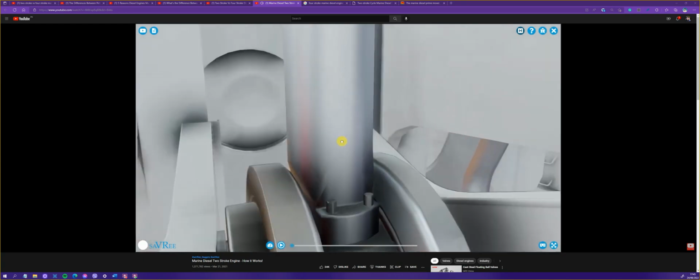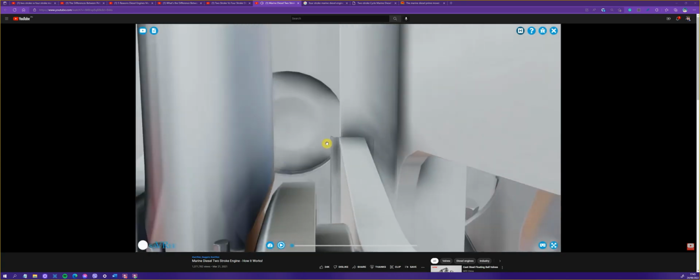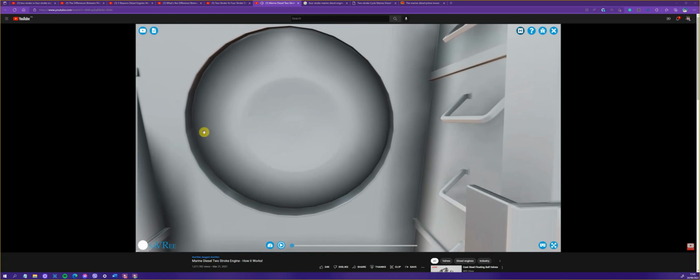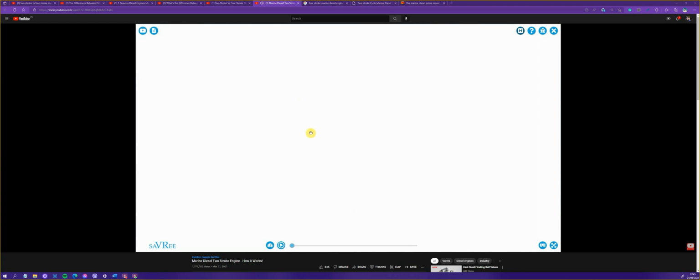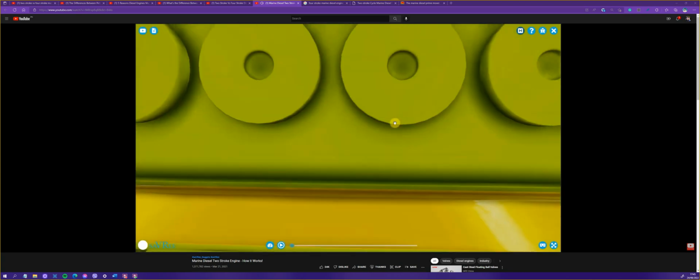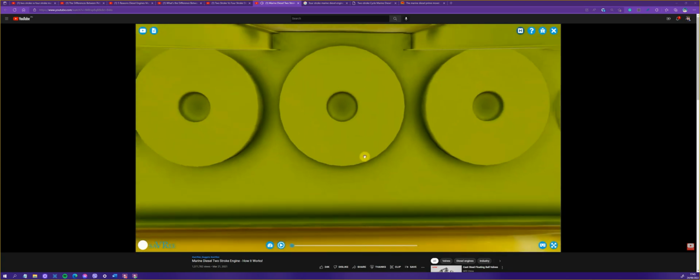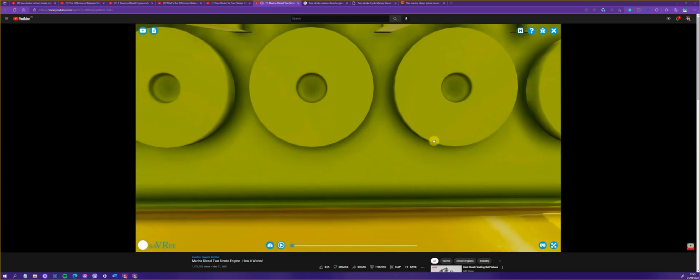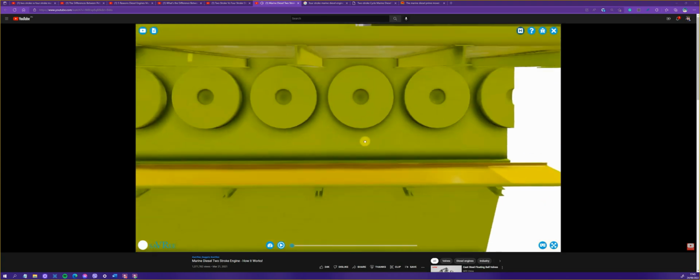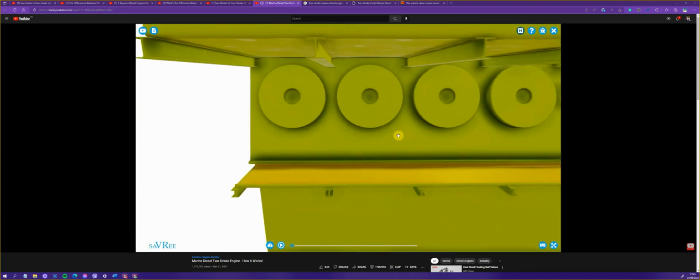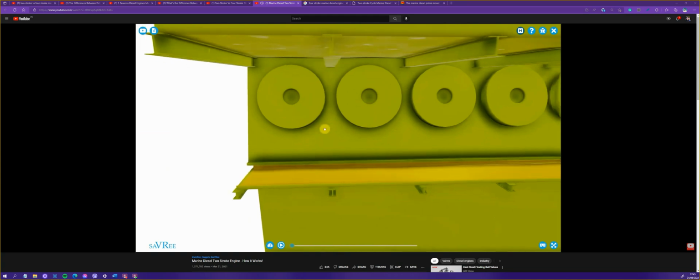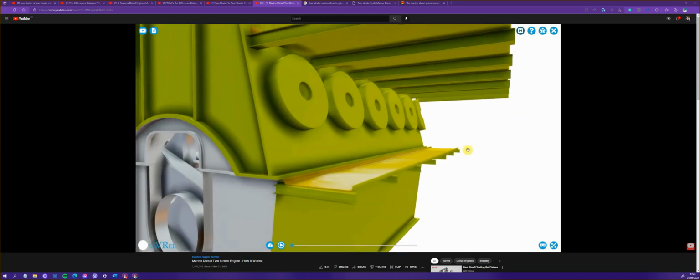Notice on the other side, go over here, this item is not a crankcase door. Let's just go out of the engine. You can do a little spin. So what is it? If it's not a crankcase door, why do we even have it? You can see there's quite a few of them. Well, the reason we have them is because they're what are called crankcase explosion doors. I know, doesn't sound very good, does it? Another name for them, which sounds slightly less terrifying, is crankcase pressure relief valves, PRVs for short.